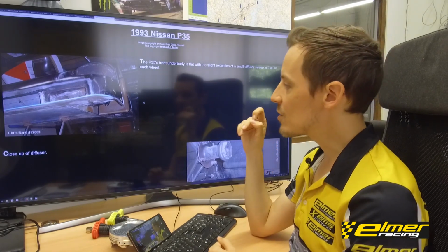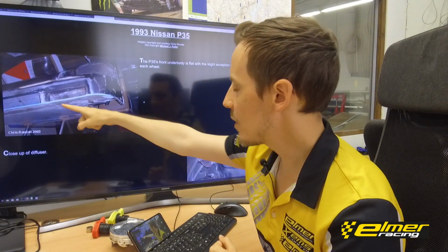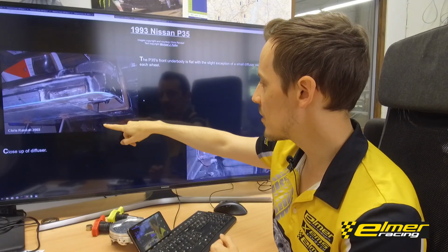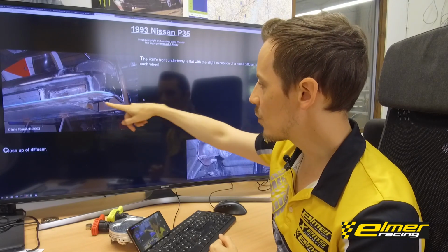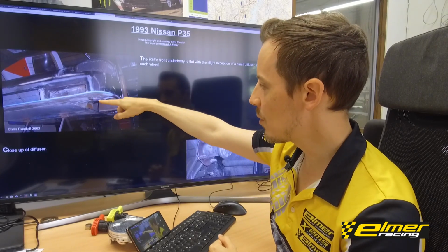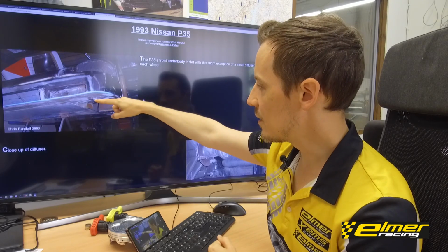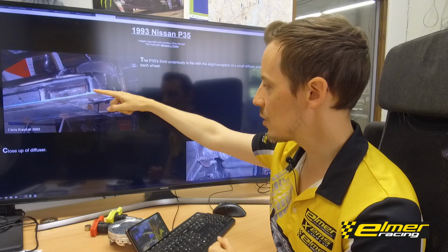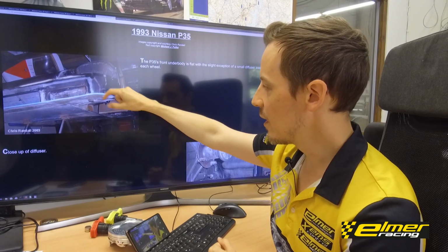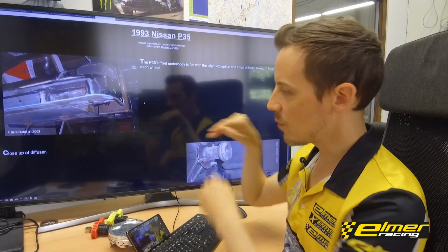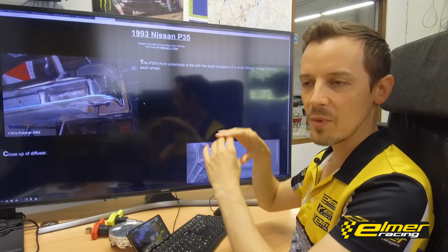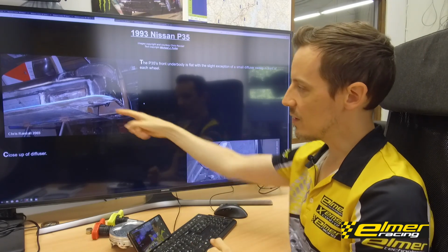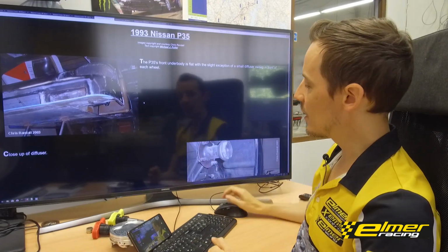So very interesting stuff. Yeah, here on the front end you can see that the floor here is flat halfway to the car, approximately at least. And for the front wheels you have a diffuser here, so this both produces a little bit of downforce here, with the diffuser in front of the front wheel, and it also helps slow down the airstream that would otherwise be hitting or diverting around the bottom part of the front wheel, and that can produce some significant drag also. So having a diffuser there is really a good solution.